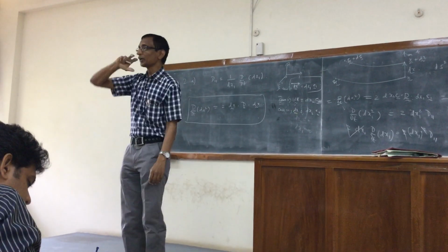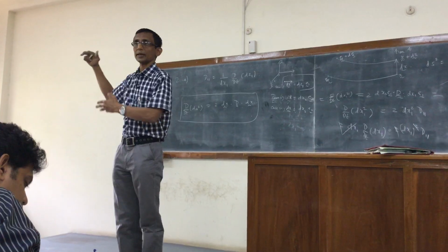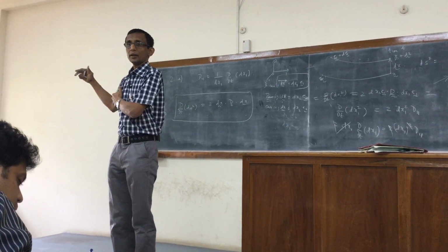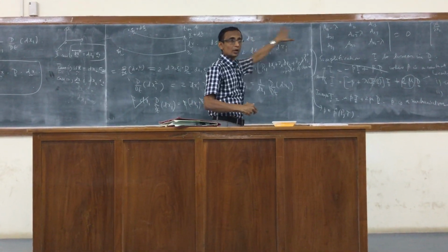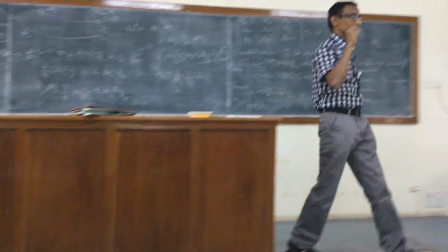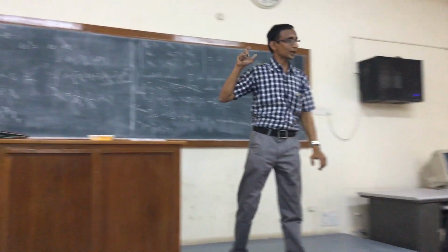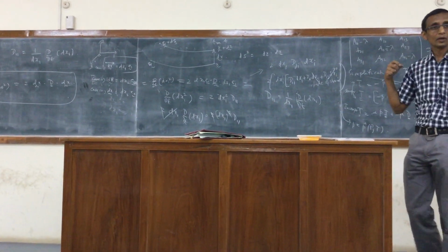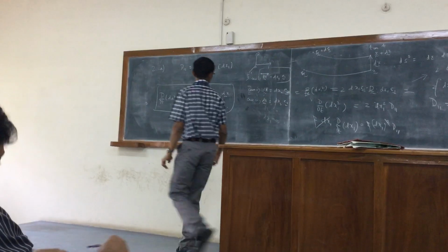In general, dx can have any orientation. It can have components dx1, dx2 and dx3, in which case I will get this entire sum, which involves all the elements of D. But by picking a particular element which is oriented along the O1 direction, I am able to give a physical meaning for the diagonal elements of D.